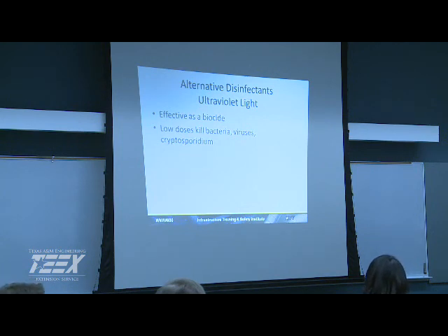It is beneficial for certain aspects. Wastewater treatment is looking at a lot of that on the UV, because then you don't have to dechlorinate. The problem is if you have turbidity issues, that really minimizes the effectiveness of it. There's a lot of preventative maintenance and upkeep on it. You've got to go in there and use acids to clean your quartz and stuff. It's a chore. And then you've got to look at your lamp hours. Expensive, a lot of energy costs.